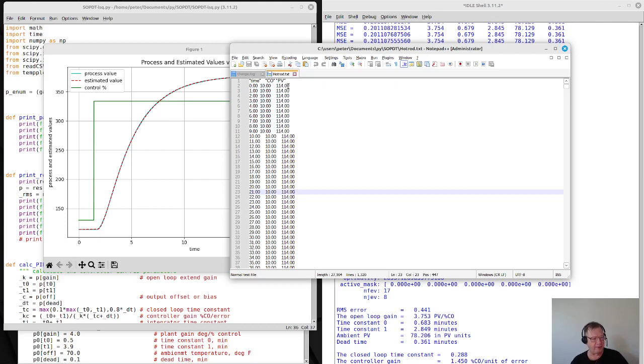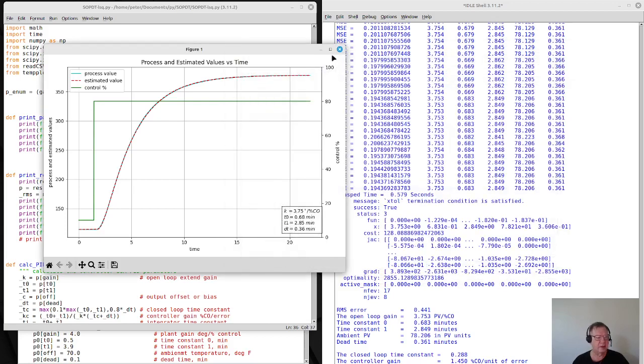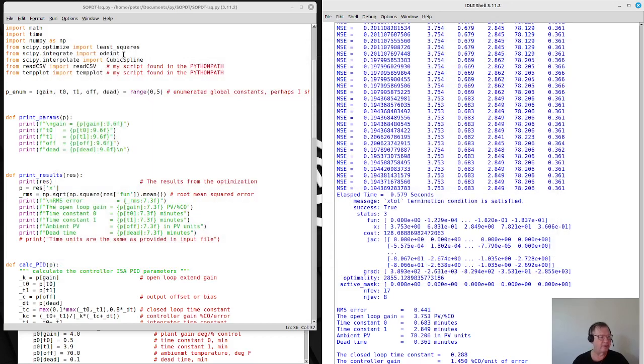And this data came from a training class where the instructor was teaching people how to do temperature control using wood burner kits. So they had a little wood burning iron with a temperature sensor on the end, and they were pulse width modulating the AC to control the temperature. So this was gathered by a trend, and then it got imported to Excel and exported as a comma separated variable file. So this is the file that's being read by this program. It's a second order plus dead time, and it says LSQ for least squares.